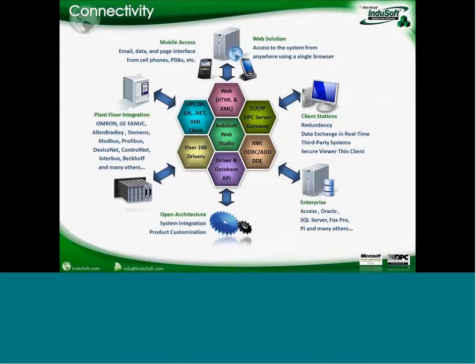PLCs, GE Fanuc, Allen Bradley, Siemens, standard protocols like Modbus TCP, Modbus RTU, proprietary protocols like Profibus, Interbus, DeviceNet, and all those drivers are installed along with the product. In addition to the drivers, we also provide the OPC client interface, so you can link InduSoft to devices in the plant floor through a third-party OPC server. In most cases, customers decide to use drivers because you have direct communication with the devices and you don't have to use a middleware like the OPC server.